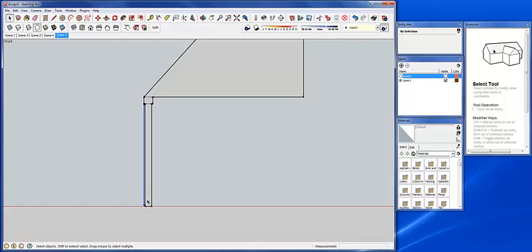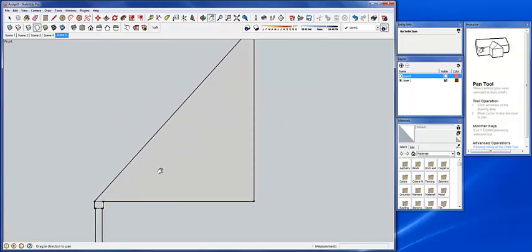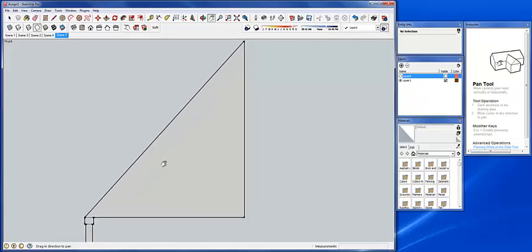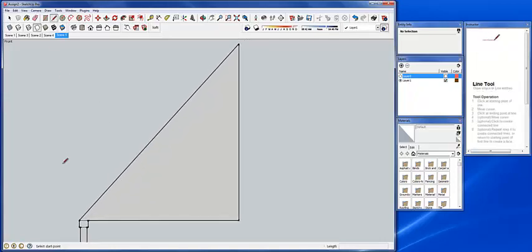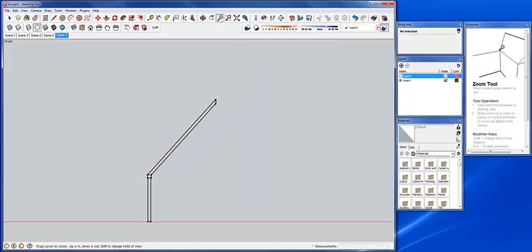Alright, and we close that off, and then we no longer need that reference line, so we can delete that. And that's a lot of what SketchUp is. You end up building scaffolds to start to build out the geometry, and then you use those as reference lines, and then you can either delete those away or you can hide them on different construction layers. So as we go in here, we know that the next point in the construction line is right there. If we want to move parallel to this line, we just roll over. As soon as it says on edge, you see that pink highlight. It means that we're running parallel to that. Okay, so we hit that, hit space. Now we no longer need that, so we can zoom out, and that's our guy.